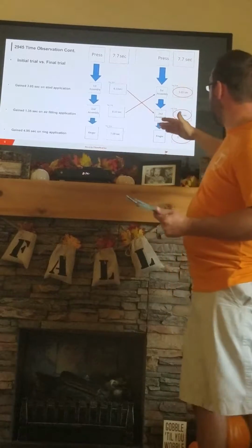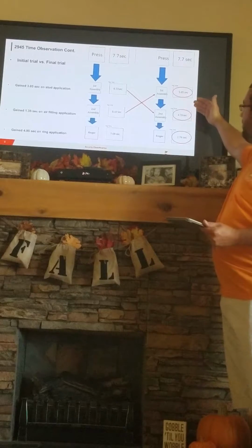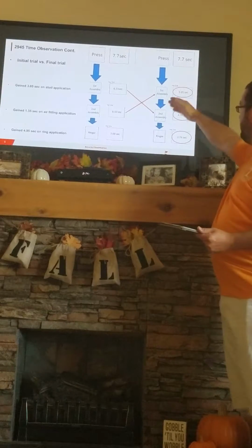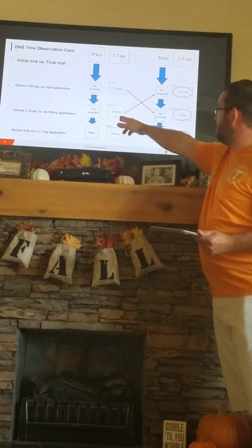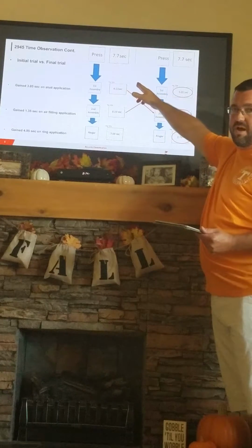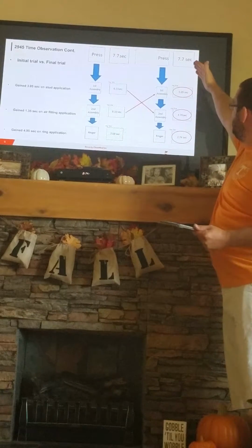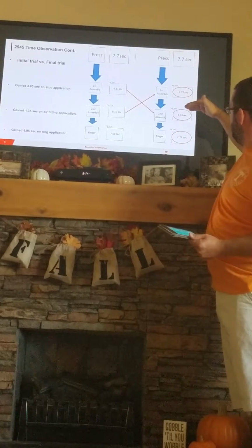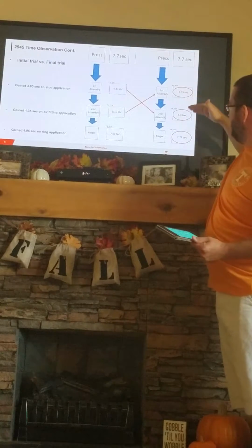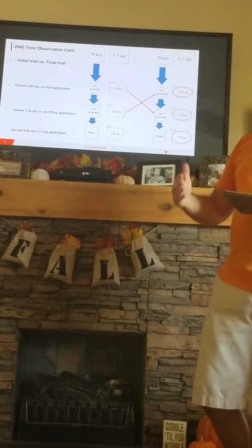So now you have the most optimal flow that we could get, versus your bottleneck being here, slower than your press's cycle time, which is feeding the line. Now each station is quicker than the press, along with each station, as you progress down the line, being slightly faster than the previous.